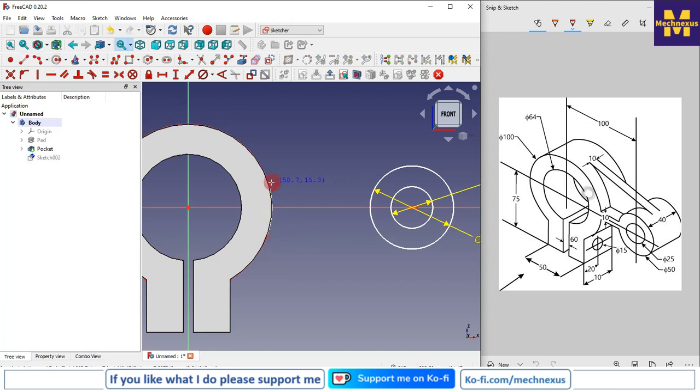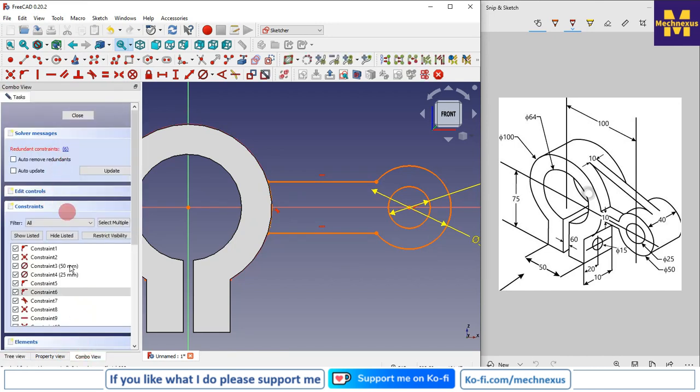And then I create two horizontal lines and connect the profile. I will remove this unnecessary arc here, so I will simply trim it, and now I will make it symmetric with my axis. So I will select this point and my axis, and I will remove the conflict, and I will say delete.